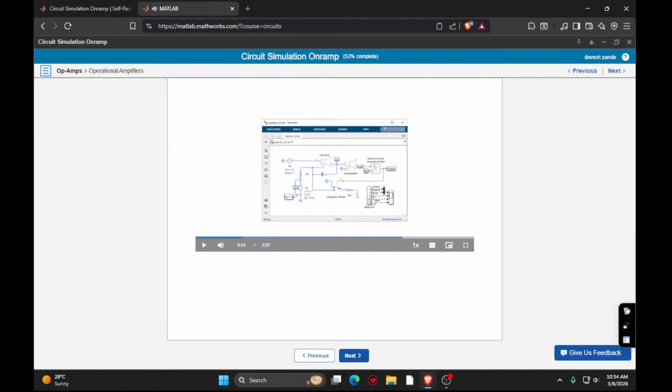Op-amps can also perform arithmetic, or you can say mathematics, like logarithmic and anti-logarithmic operations, and because of that we can also do mathematics like multiplication and division. But because the op-amp gives gain at the output, we have to set the values of the resistors R1 and RF to make the gain minimum, so the output will not be saturated. Okay, so we will learn about that later.